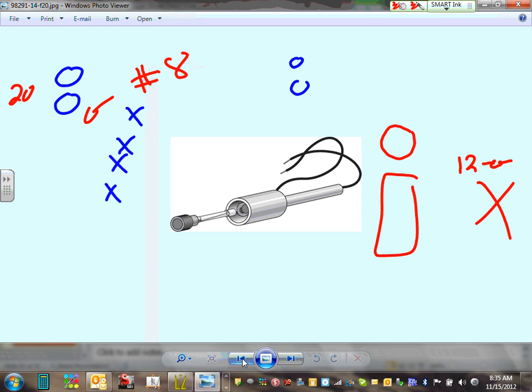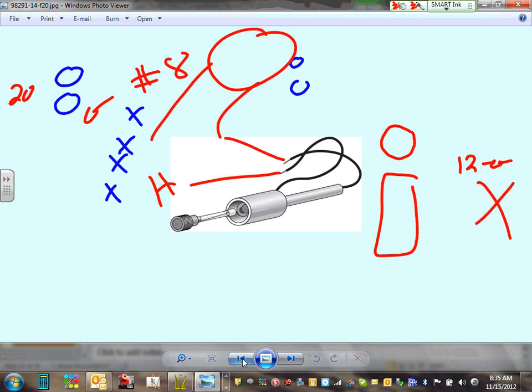Here's how it looks. Jeff, my friend, you bring your voltage here, you bring your hot here, and you take the hot, and the neutral comes to the lighting fixture. That's how it typically goes. And if you have a short circuit, that inline fuse is right inside the base of your fixture, the base of the pole, right? You're going to find that little inline fuse.